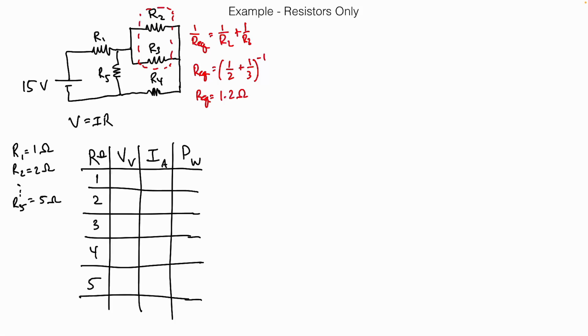So that combination. And so my new picture now is a battery with R1. And then like this new resistor that's right here. There's a junction right there. That goes to 5. So now I've got my 1.2 ohm, and that's connected to the 4 ohm like that. So the 1.2 and the 4.